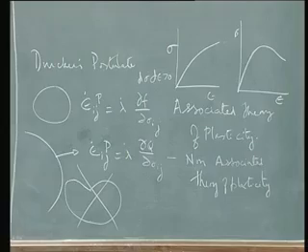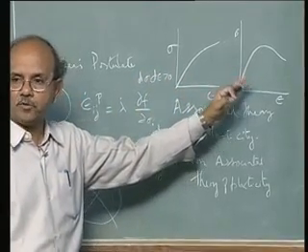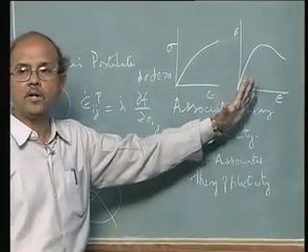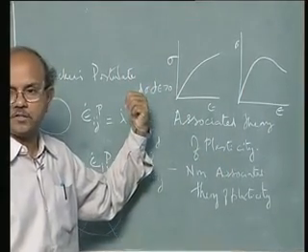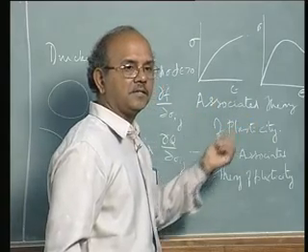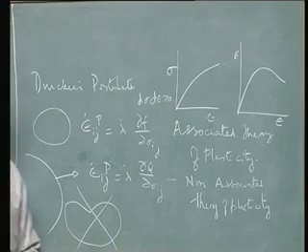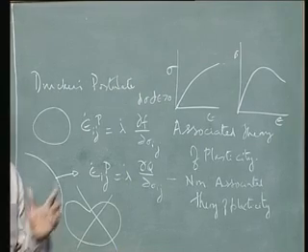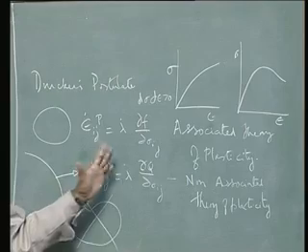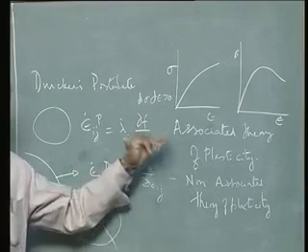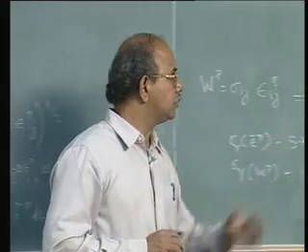It is not that these are the only materials that are available. There are materials like this. Most of the civil engineering materials would not follow this associated theory of plasticity, and hence Drucker's postulate, and hence may not follow many of the consequences of this. So these are what I would call, within quotes, unstable materials. So in this course we are going to concentrate only on associated theory of plasticity and stable materials defined by the Drucker's postulate.